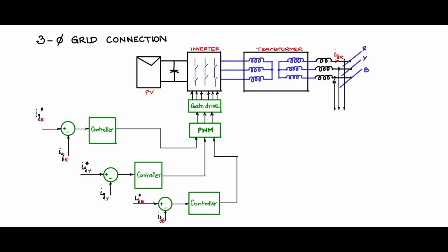You could use a Hall sensor, or you could do it with resistive shunts and differential amplifiers, instrumentation amplifiers. But measuring it with Hall sensors is recommended because it is contactless and has a very large bandwidth.